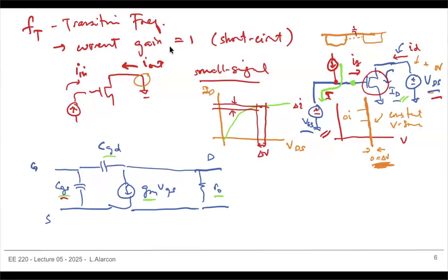So in your homework, you'll see that one way we can get around that is to put in a very large inductor. What's nice about this inductor? We normally just call that L infinity, ideally. Why is that? Because an inductor in DC is a short. That means in DC, I can provide the VGS to the transistor.